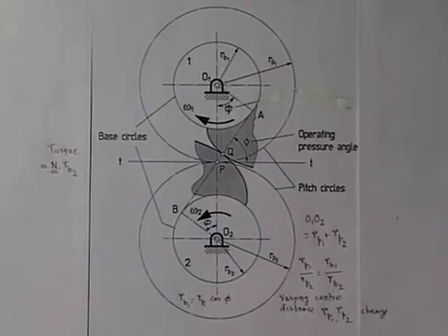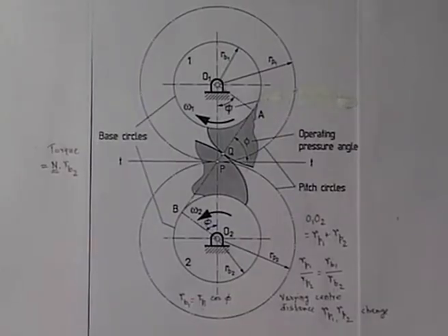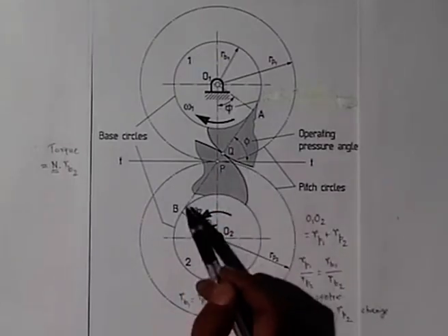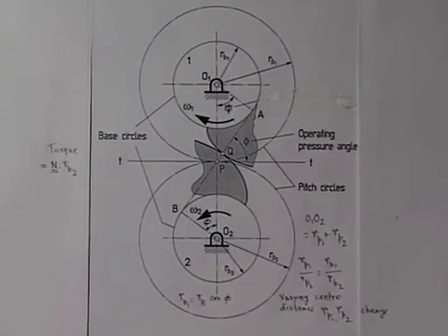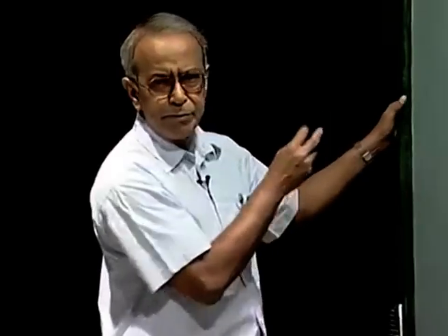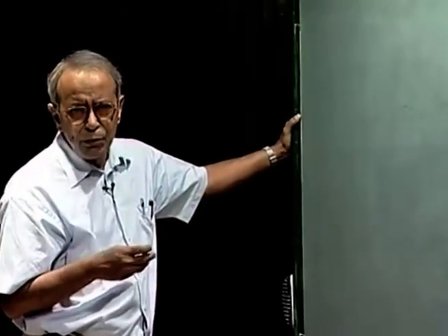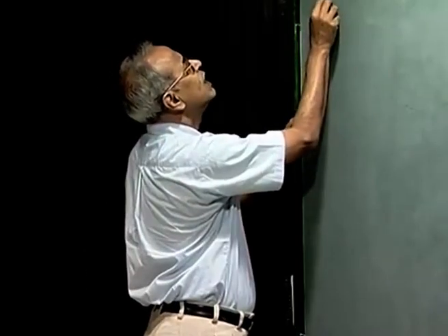And the fourth advantage, as I said, will be explained later when we will be able to show that the involute of a straight line is a straight line, that is, for a rack to maintain conjugate action with an involute profile, the tooth profile on the rack will be straight, like a trapezium, as we have shown earlier on the board. Because involute profiles have all these advantages, as I said earlier, they are almost universally used in mass produced gears, and as a consequence of this mass production of involute gears, they have been standardized. There are various standards, but I can mention some typical standards which are more commonly used, like the British standard for involute profiles.